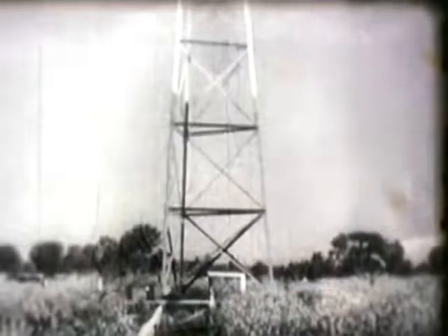A half-wave antenna should measure half the wavelength of the frequency employed. This broadcast antenna measures approximately 309 feet. It operates on a frequency of 1590 kilocycles, corresponding to a wavelength of about 618 feet, or twice the length of the antenna. As radio frequencies decrease, wavelengths increase, and the length of the antenna must increase, so that some radio frequencies would require a half-wave antenna too big to be practical.